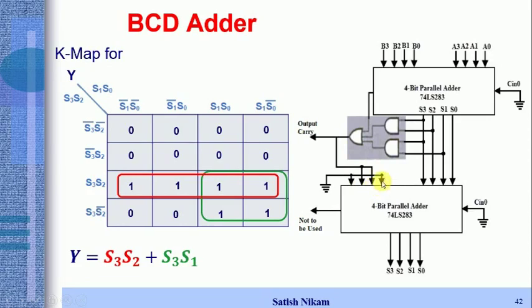If you check here, the B0 and B3 bits are connected to ground, so this becomes 0, 1, 1, 0. This means when we get a high output from the combinational circuit we designed, 6 gets added to the result. Otherwise the output is 0, and we simply add 0 0 0 0 to the result.